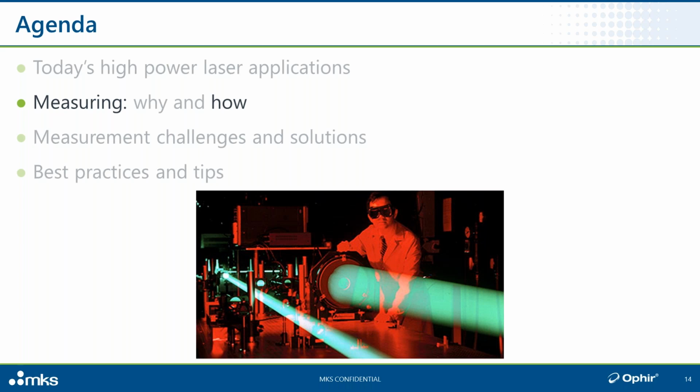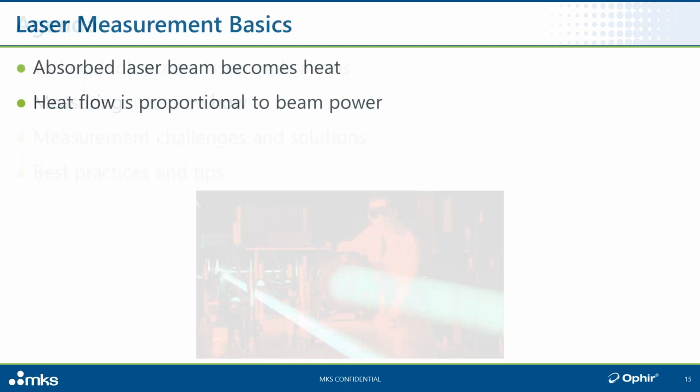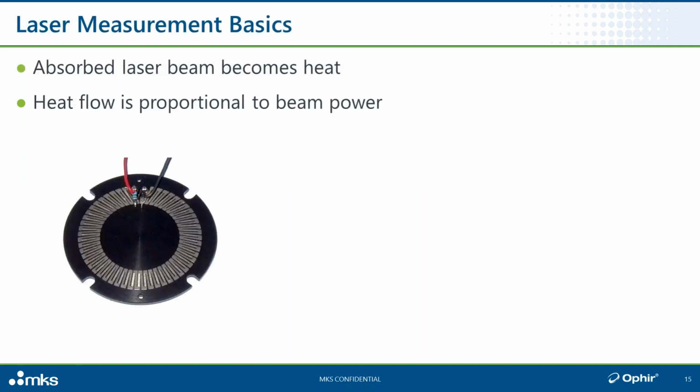Briefly, how we measure. We're not going to go into the engineering behind every possible method, but again, just to give meaning to the rest of our conversation. So here, again, a generic type of laser power sensor for the sort of moderate and high power levels that we're talking about when we're talking about high power industrial laser beam applications. So here's a pretty typical sensing element of a laser power sensor. You've got a metal disc, you've got a thermopile ring.